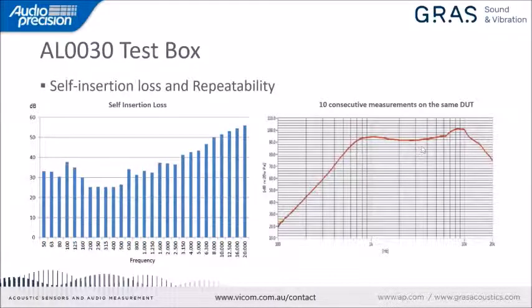So the way these test chambers are used is the following. First of all, we select a golden device. This could be a tablet or laptop that, after proper testing in a hemianechoic chamber or with a trained listener, we all agree is performing in the way we want. Once we do that, we grab this golden device, and we place it inside the test box and perform the required acoustical tests.